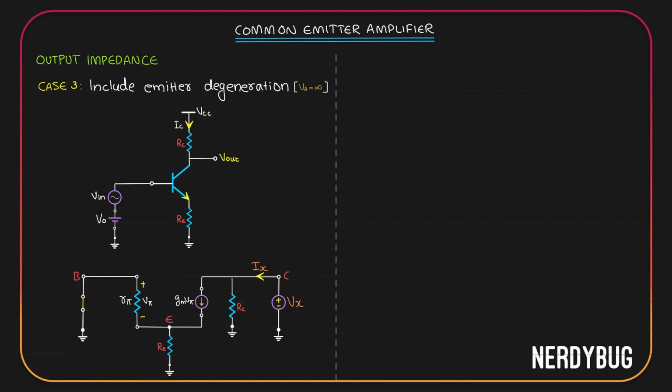So whatever is the potential across R pi, it is going to be exactly the potential across Re since they are in parallel. Negative potential of R pi is here. Since it is connected to this end, Re will get negative here. Positive potential of R pi is here. Since this gets connected to this end of Re, it will get positive potential here. Basically, Re will have V pi across it. Let's write this down. R pi is parallel to Re, so Vre is equal to minus V pi. Why minus? Because we got negative here and positive here.